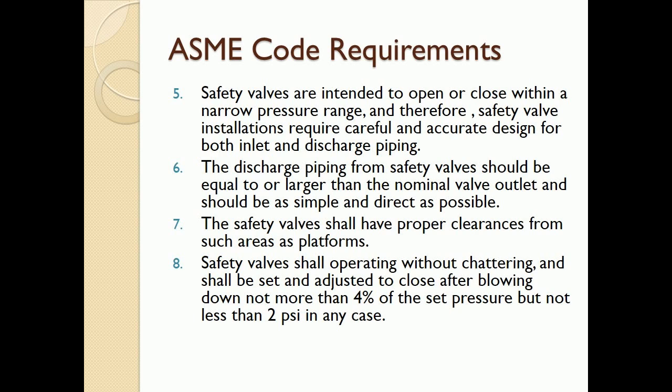7. The safety valves shall have proper clearances from such areas as platforms. 8. Safety valves shall operate without chattering, and shall be set and adjusted to close after blowing down not more than 4% of the set pressure, but not less than 2 psi in any case.